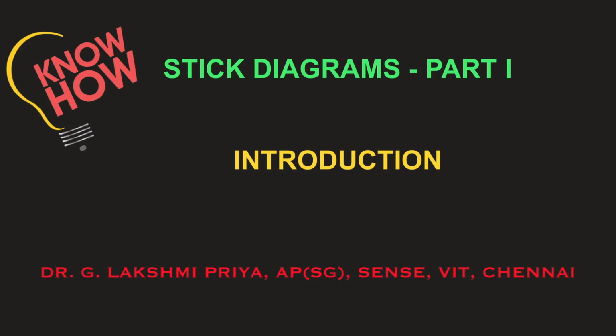In this, the designer draws a freehand sketch of a layout using colored lines to represent the various process layers such as diffusion, metal, and polysilicon. The main advantage of this symbolic approach is that the designer does not have to worry about the design rules, because the compactor ensures that the final layout is physically correct.